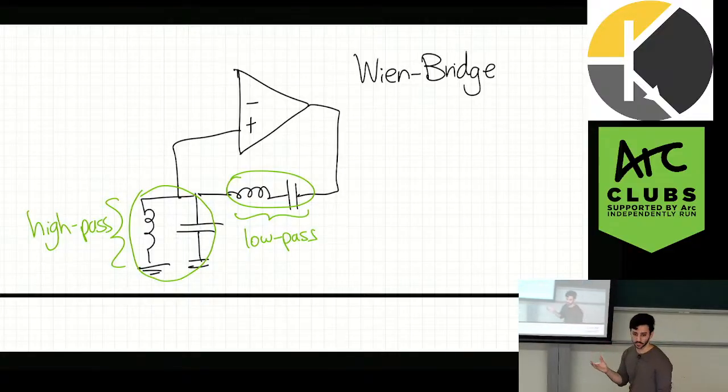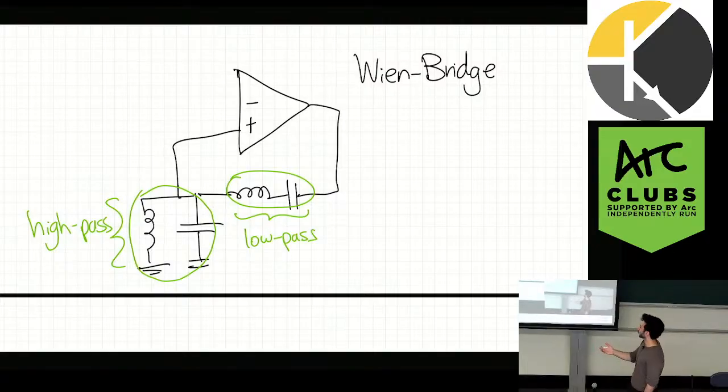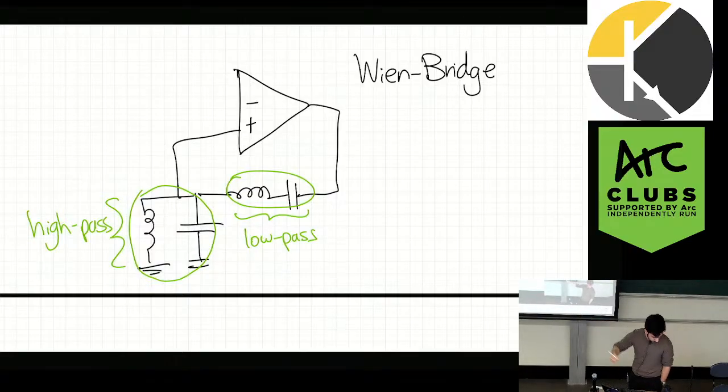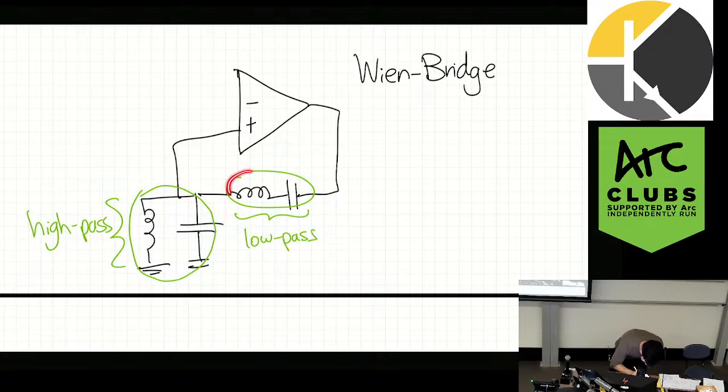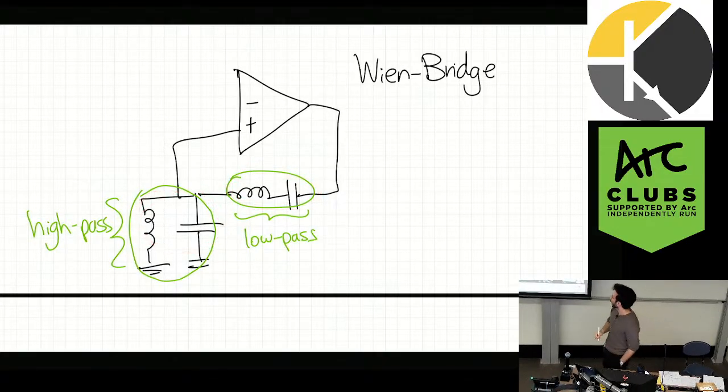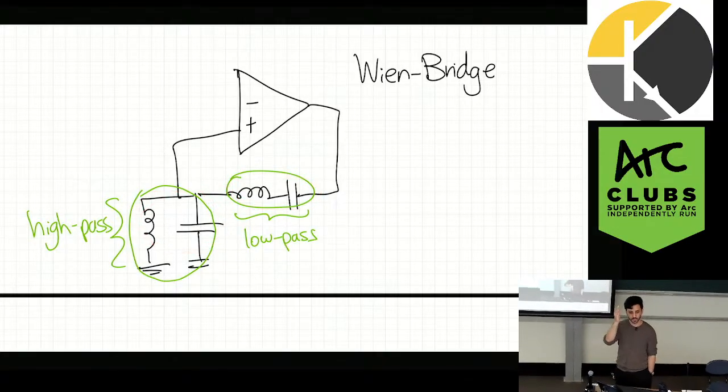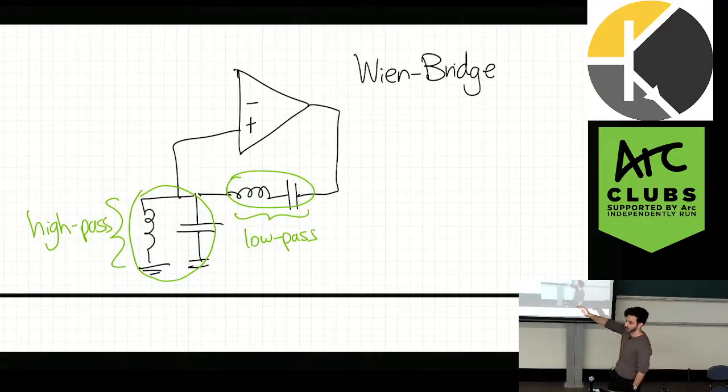It's the same thing as what we just had in the Pierce oscillator case. Again, it's another filter in the feedback loop that's going to pick one frequency, and that's the frequency this oscillator is going to run at. Now, in this case, back to your point, Otto, this has a 0-degree phase shift. At this particular frequency, there are inductive and capacitive elements, and at the resonance frequency we know that the phase shift is going to be 0, purely from this filter. Again, ignoring everything else, we're just looking at this filter. Yes.